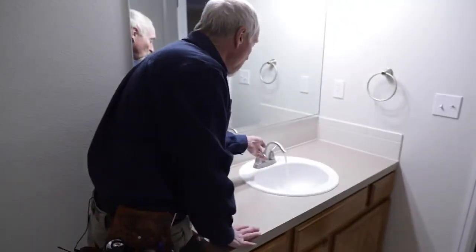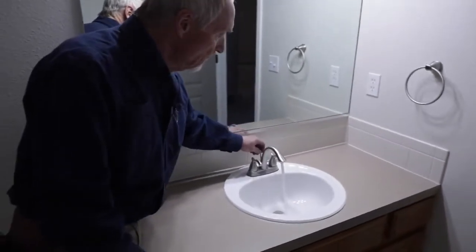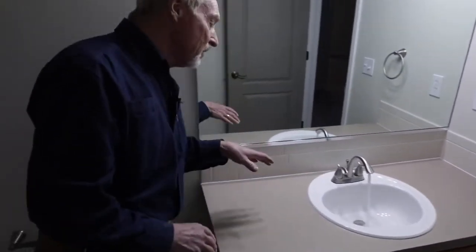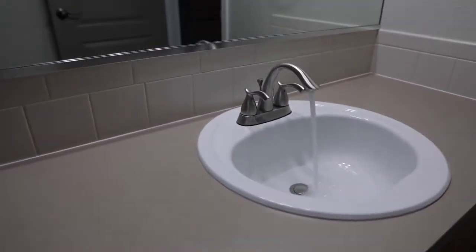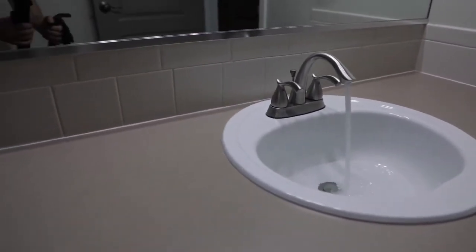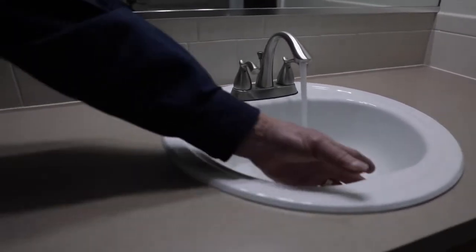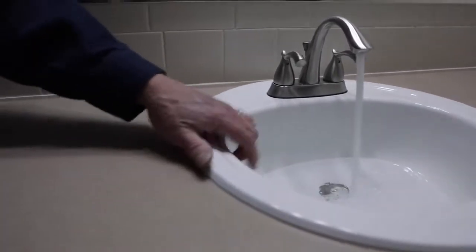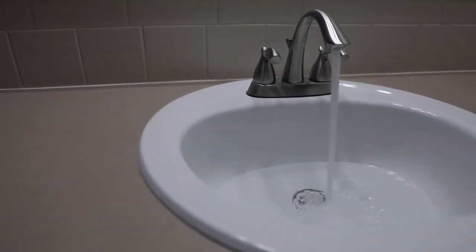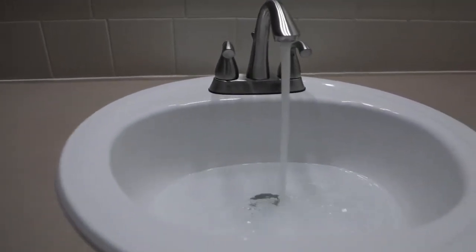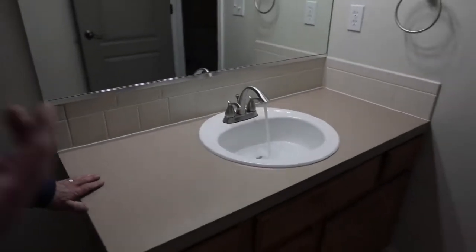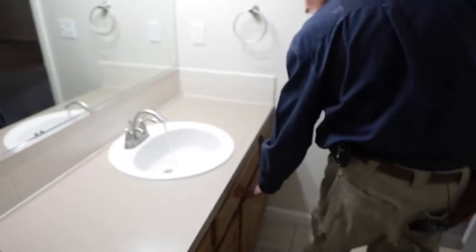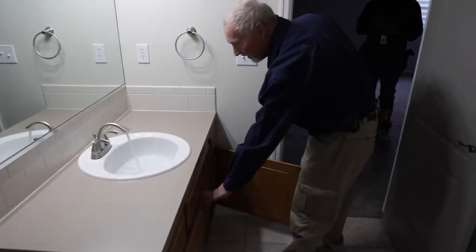So over here with our sink, run some water. I like to close off the stopper if it'll close off, and add some water to the sink. I'll fill it to the overflow holes. In this case, this is a steel sink. Steel sinks typically are a little more vulnerable to having problems underneath than ceramic sinks. So I'll run some water in here while that's filling.